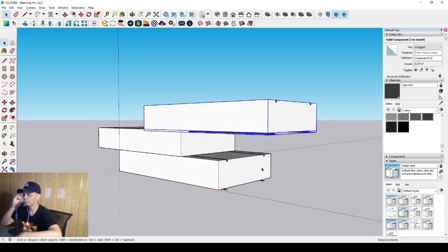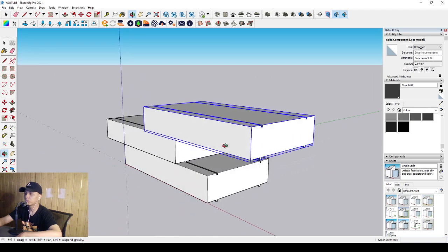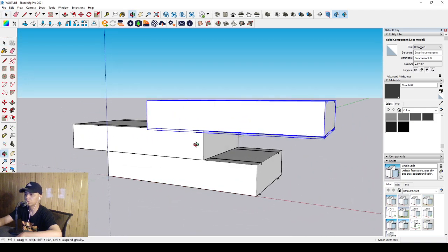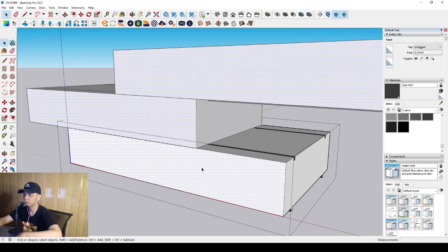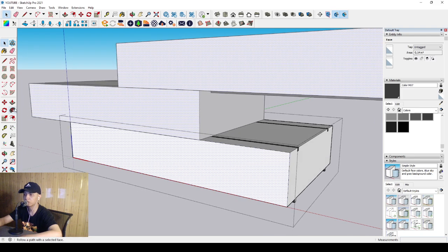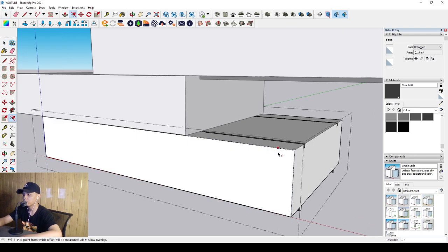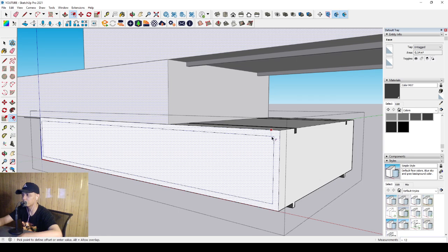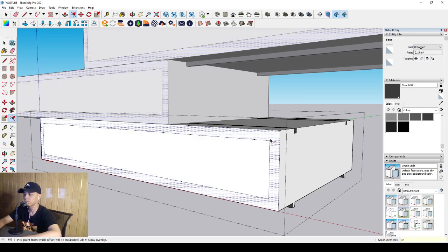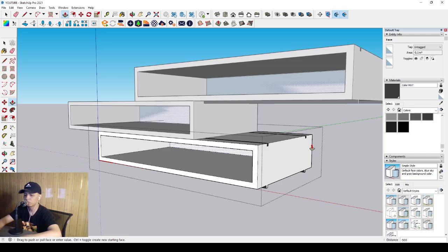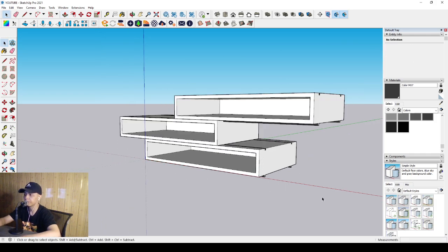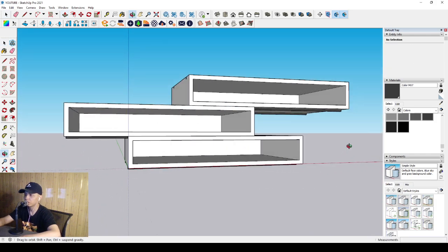And after that, we can also make the drawer of every single table in here. We can select this front panel over there. We can offset it inside. Okay, we can offset it inside around 20 millimeter, for example. Then we can push it to the background 400, 480 millimeter, just something like this. Okay, so you can see it.